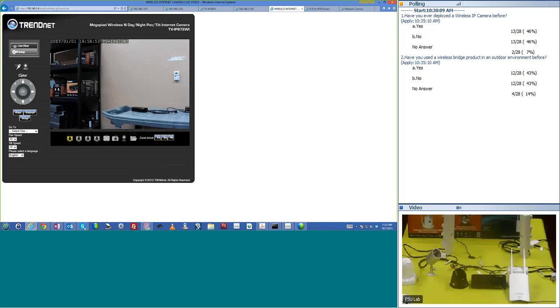And I've been testing the throughput on this little Ingenious access point to see if it could handle all of the different things. Now, I put up other cameras besides the TrendNet camera as well. And I was able to do 30 frames per second, motion JPEG. I did put a 5 megapixel camera, motion JPEG at full frame rate at like 15 frames per second. And the access point handled it with no problems. Now, I haven't tried it with like 10 of them, but maybe I will one of these days, and we'll see if it handles it. But one camera seemed to work out great.